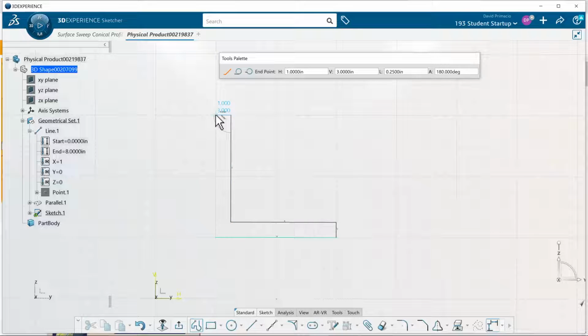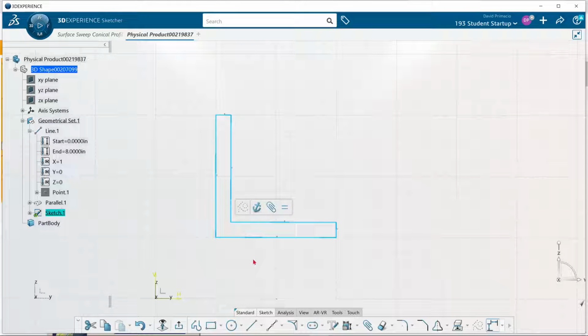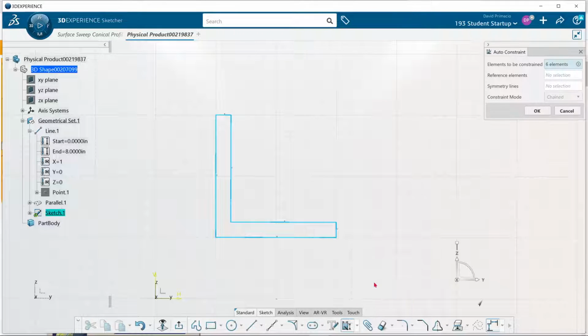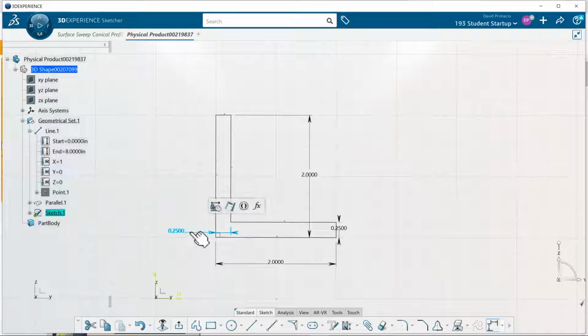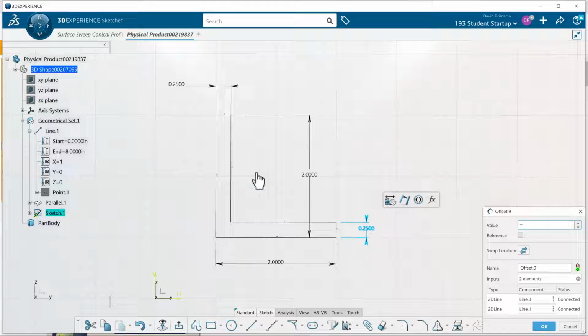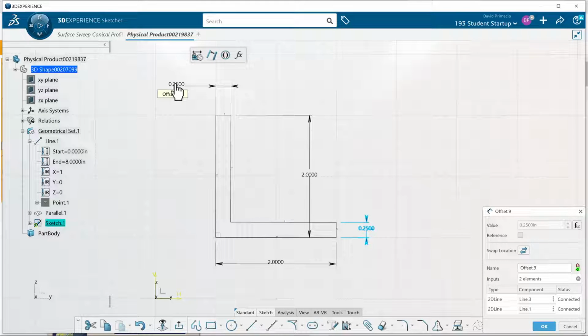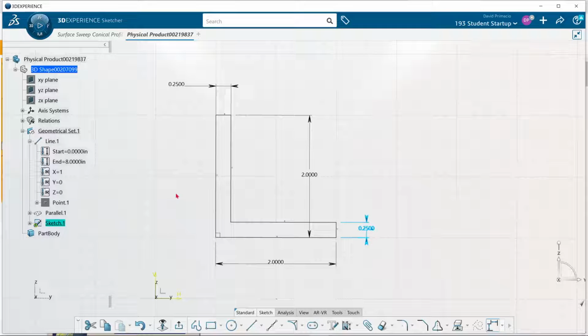Do 1/4 inch gauge thickness for the angle bracket. And I'm going to go right to auto constrain and reference these 2 lines. I'll stack dimension. So I got these. Oh, shoot. If I wanted to make these the same, you can double click it and hit equals and click another value, and they'll equal each other. So if you change one, it'll automatically change the other.